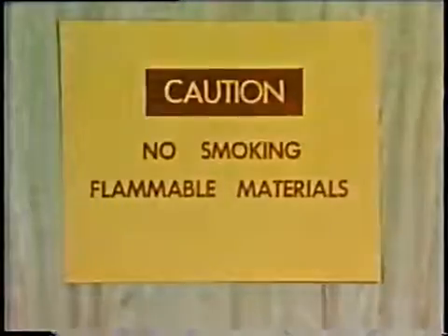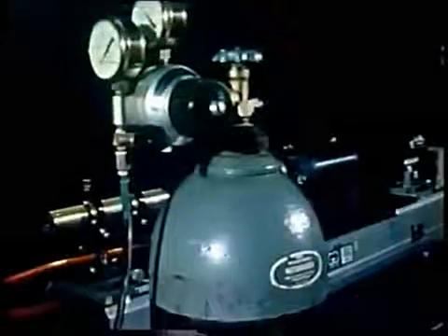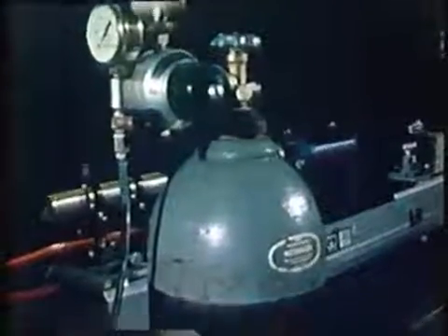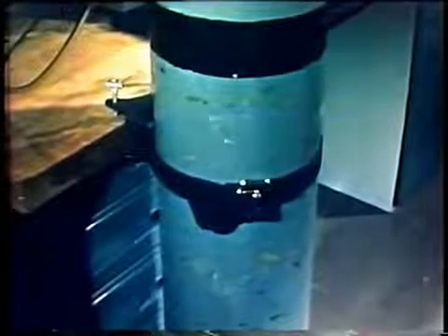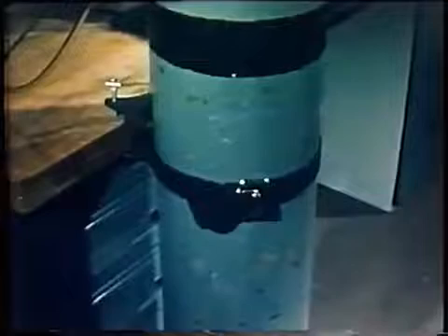Cryogenic materials can be dangerous. This bottle of dry nitrogen should be strapped securely to a solid object. Should the bottle fall over and the regulator break off, the gases will propel the tank with extremely destructive force.